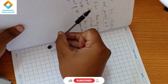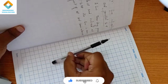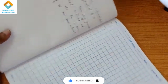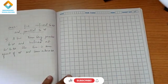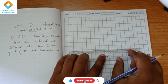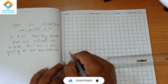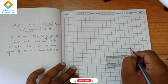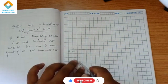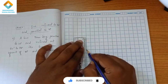Parallel to the VP means we get a straight line. Inclination to HP means either it is 30 degree, 45 degree, 90 degree. So this is the inclination to HP and parallel to VP, and this is how we have to do it. For that, first I am going to draw the XY line and the first quadrant. VP, HP, XY. You can see here the end of the line is 20 mm in front of VP, 30 mm above HP. So 30 mm above HP means this is 30 and this is 20.